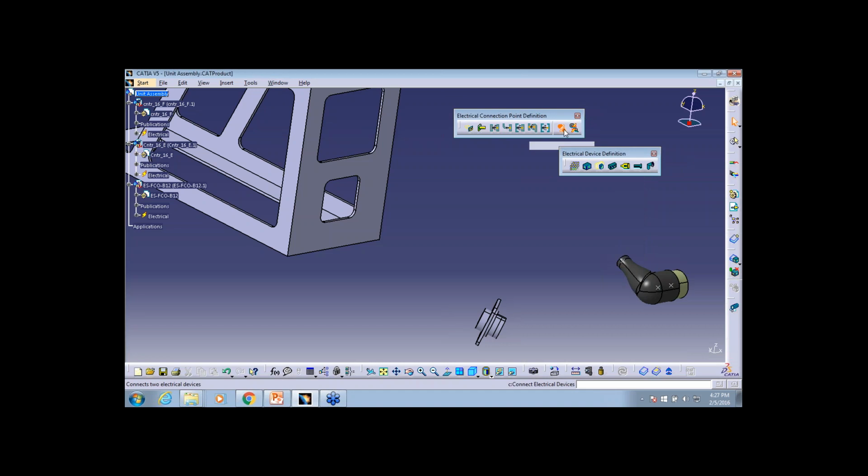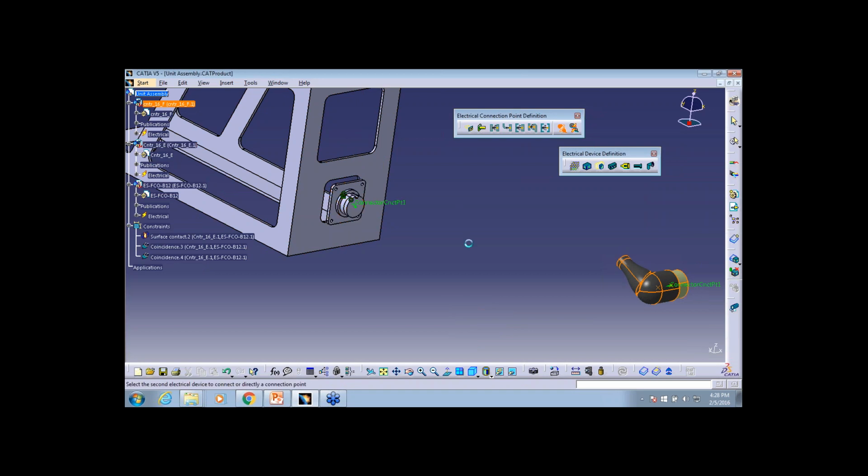So I'm going to connect this component with this connector. You can see that it goes and sits automatically. This is nothing but your assembly constraints, all the assembly constraints which we have defined as an electrical property. Now I want to make this component go and sit. So I'll connect this one with this, and it sets automatically. So this is how your standard components are created, and in your electrical assembly design, you have your electrical components positioned here.